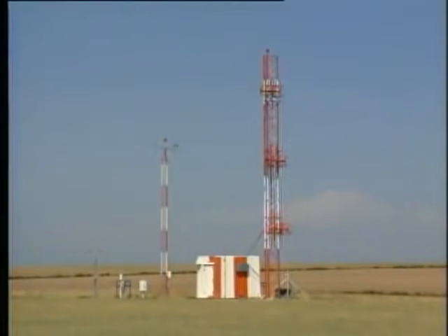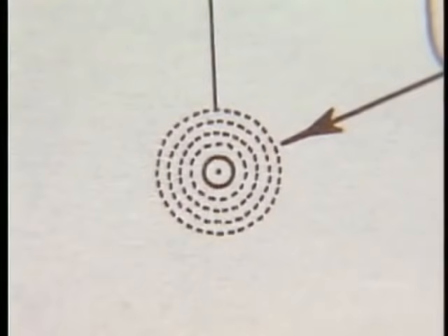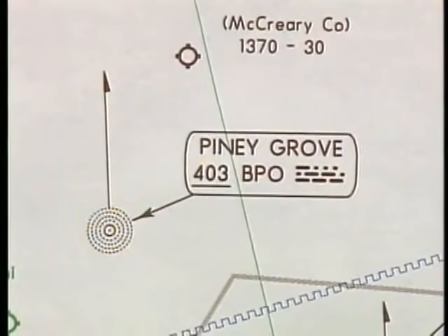Non-directional beacons are low or medium frequency nav aids generally associated with instrument approaches. The location of an NDB is marked by a series of concentric brown dotted circles. Information pertaining to the facility name, frequency, and identifier are located near the symbol.